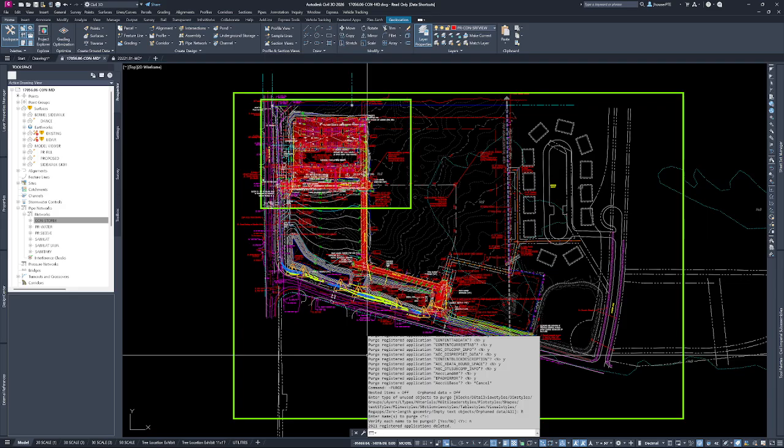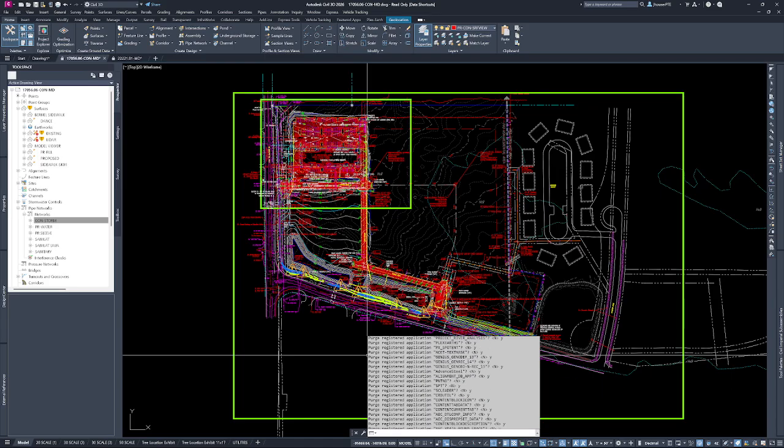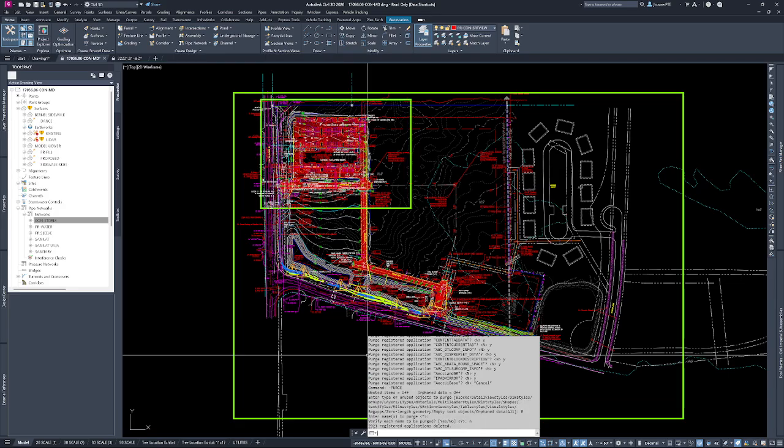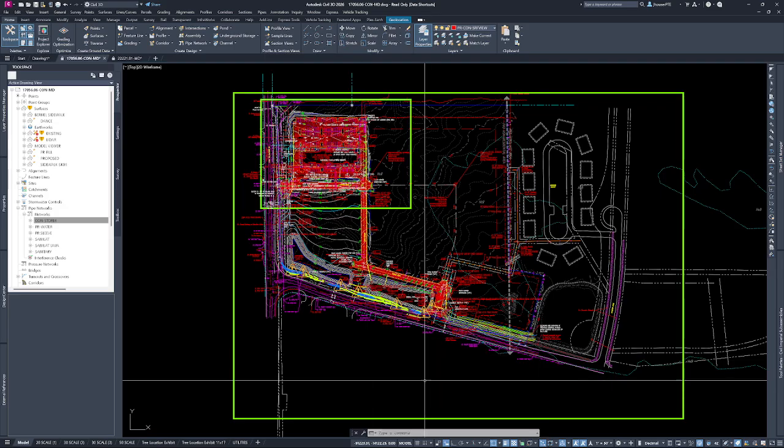That will help speed your drawing up and get all that extra information that's not being used out of your drawing. Again, especially when it's coming from other architects outside of our office, any files outside of our office, anytime we block things in, this stuff can be left behind and clog things up and slow things down. Not something I really knew about until recently. We were able to run this on a project that had quite a few different references to outside files, and it made the project run much better. So that's a good way to really clean things up.